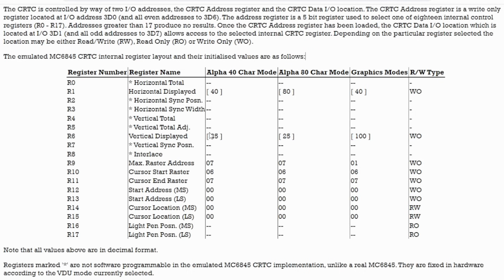Now that might seem limiting. On CGA I can set the vertically displayed number of character rows to anything I want, regardless of graphics mode, whereas here it's fixed for basically full screen display. Now, it says in the manual that if I put 0 in these registers, it will just display the border color and it basically turns the display off.